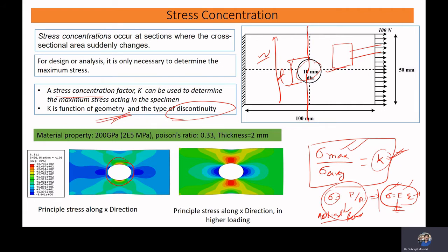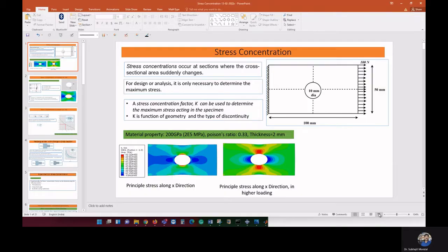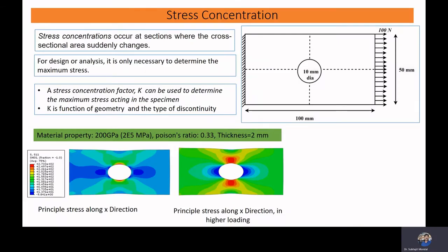Okay. So now, if we have a plate and we make a cutout like that, we will observe that stress is very high in this zone. If you have a plate and you are applying load like this, you will observe the stress is very high in this zone. So here you can observe that stress is concentrating in this zone.